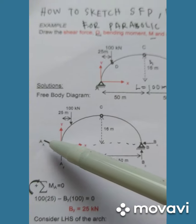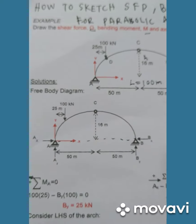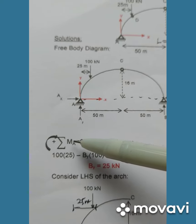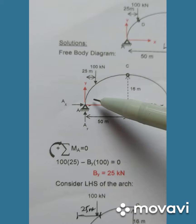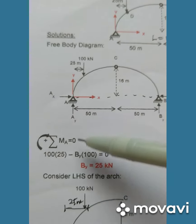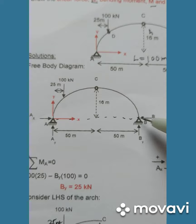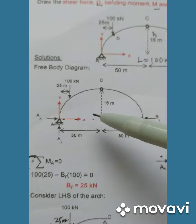So AY, AX, BY and BX. You have to find AY, AX, BY and BX. First, we calculate By by inserting into the total moment equation. So 100 times 25 minus By times 100. So By we get 25 kilonewton. Bx cannot be inserted into this equation because Bx is on the same line as A, so there is no distance for Bx.